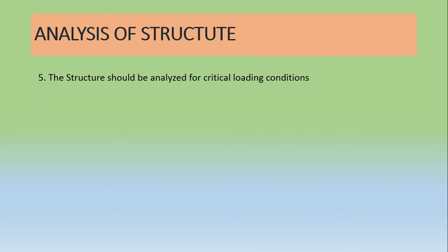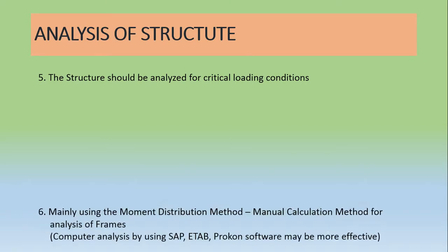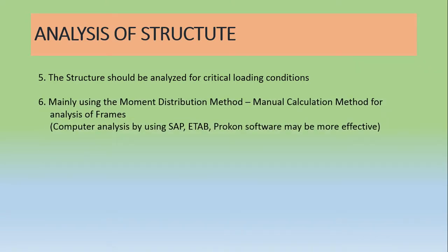The structure should be analyzed for critical loading conditions. You know that I told you we have factored dead and wind loads and then added. Those are the critical loading conditions, so when you are designing you should consider them.